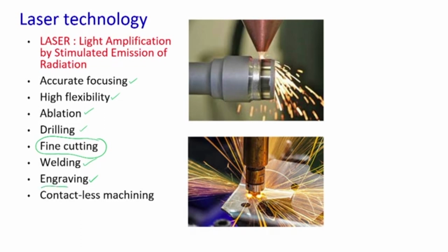We will be seeing the engraving operation in the next week. The biggest advantage of lasers as far as material removal is concerned is contactless machining. We have seen some of the problems with mechanical material removal, which is a contact operation. Wherever there is contact, there is friction, noise, vibration, wear and tear, and it consumes a lot of energy as well. So, can we have contactless material forming? The solution is by using lasers.